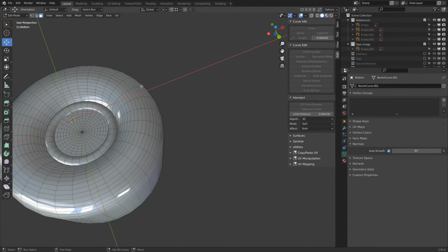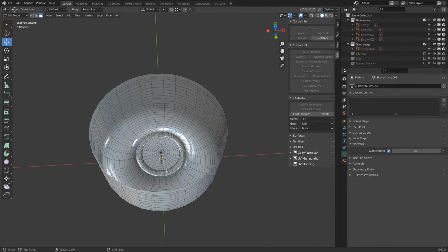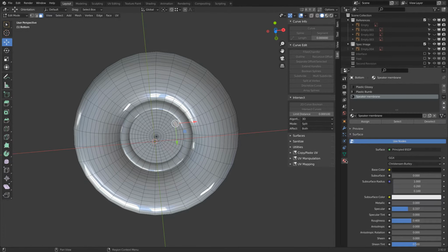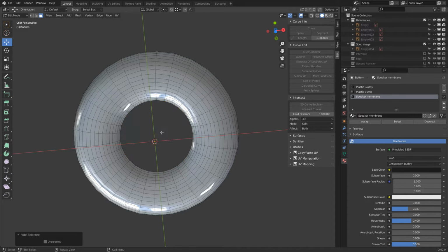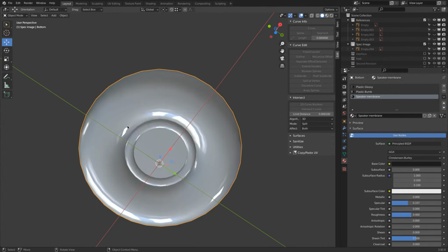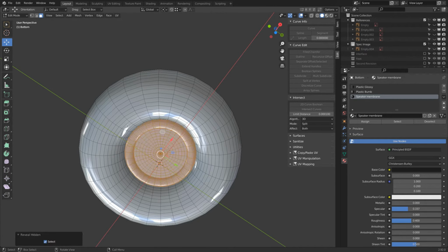So why did I do this? We want to select through the whole object, and I want to prevent these things being in my way. So when I go to material and select this, I select the material, that selects in all the mesh, and I can press H, and then the mesh is just hidden. Cool thing is, press Tab in object mode and the mesh is back. Tab, go into edit mode and the mesh is there. Alt H shows it again.